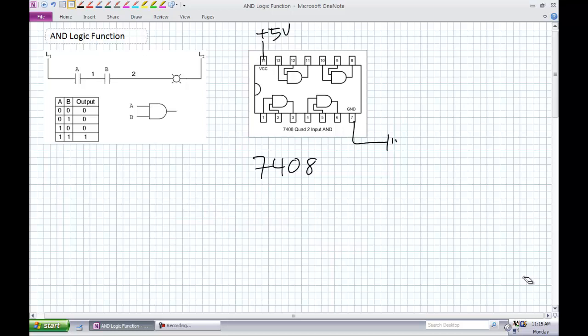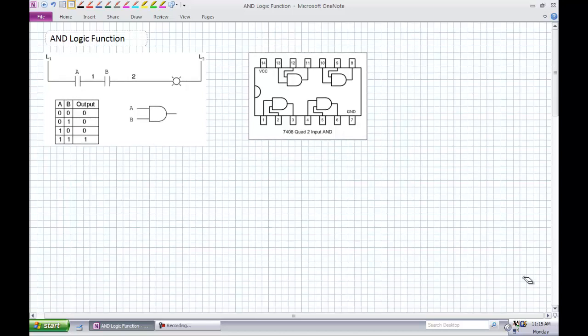We mentioned the data sheet, and we talked about writing these things out as timing diagrams. How is the AND gate applied? It's a pretty cool gate, and you may have seen this diagram before in motor controls. This is really the major purpose behind digital electronics. Besides doing all the whiz-bang stuff with computers and memory, it is essential to your understanding of motor controls and PLCs. The AND gate is what's known as a permissive, a safety chain.